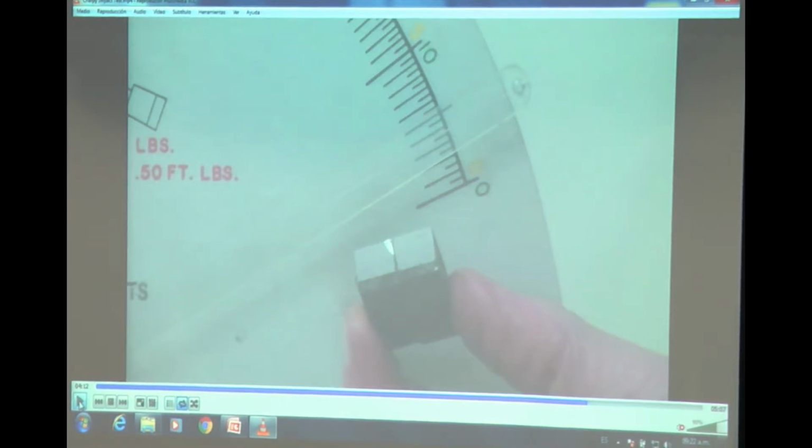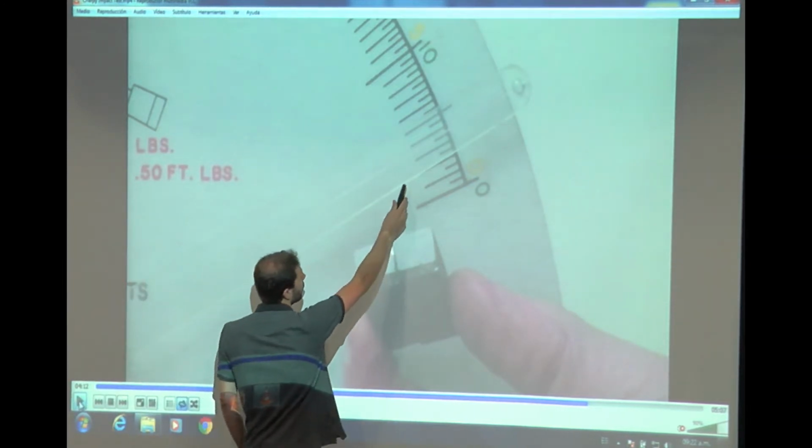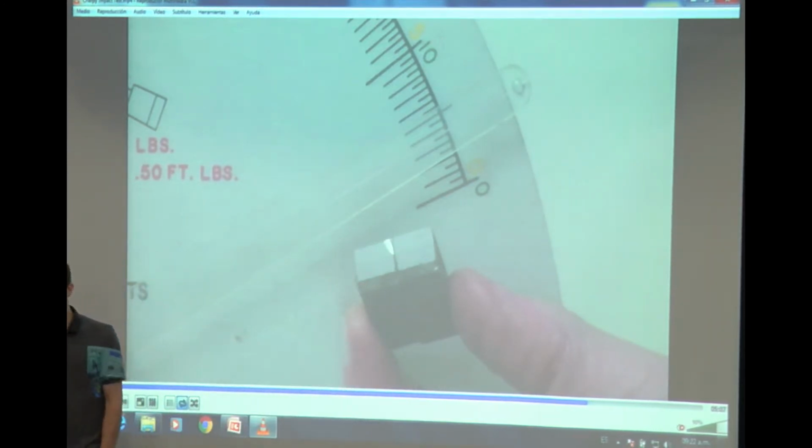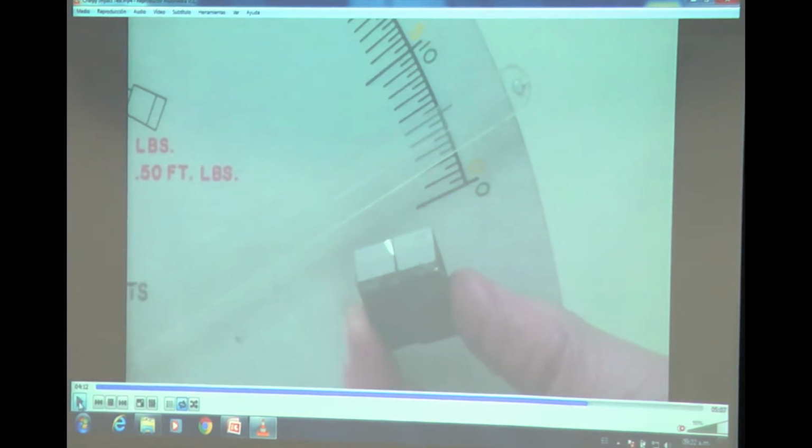And you also can see it, for example, at this part, at the surface itself, but also compared to before, we had here information about our Charpy energy of 28, and now it is 3.5.